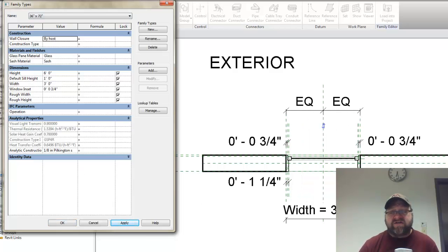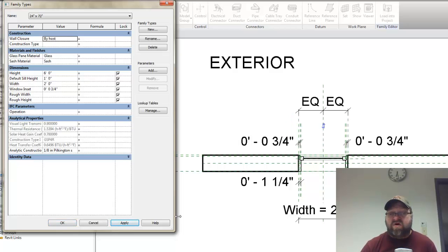We actually go through this kind of process when we make our family. We build up the geometry and these different constraints one at a time and do this testing and flexing to look for errors the whole way through while we're building the family, because we don't want to build a complex network of things and only find out we made a mistake very early in the process, and then everything doesn't work, and we have to spend a lot of time undoing that.